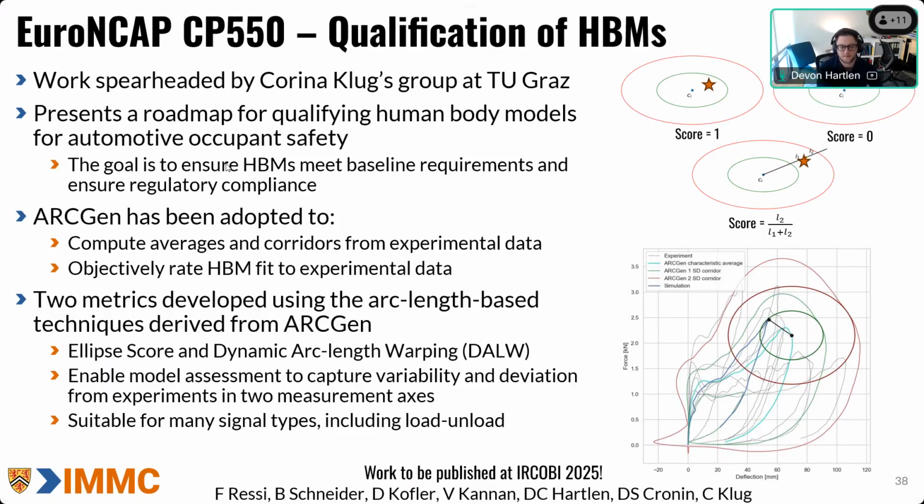My suspicion is no, but at the same time, one of the other things compared to the ISO standard or the CORA is that the corridors are actually quite a bit wider with the ellipse technique, because we're using standard deviations as opposed to a scaled value based on peak magnitude. So you're trading off in both cases. But absolutely, this is a more complex method. But in my opinion, we're dealing with more complex problems. We need a better way to actually evaluate those techniques.